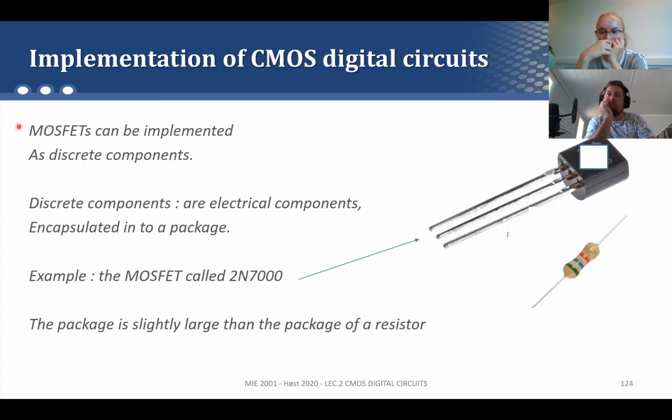But here I was expecting maybe that someone of you has some question, like why there are only 3 terminals rather than 4. And the reason is that this MOSFET is mainly used for, okay, first of all, it's very old, but it was used mainly for analog applications. And in analog applications in the past it was very useful to connect the bulk terminal to the source of the MOSFET.